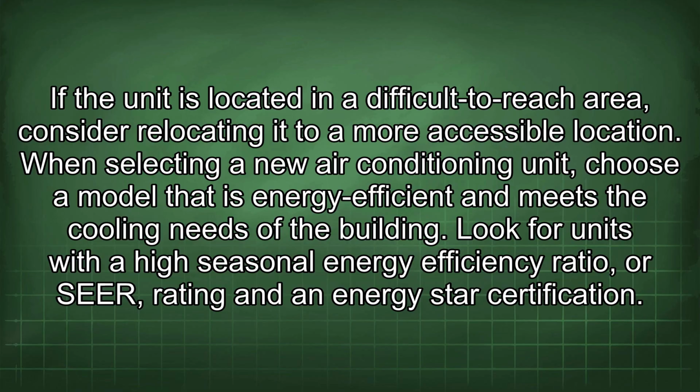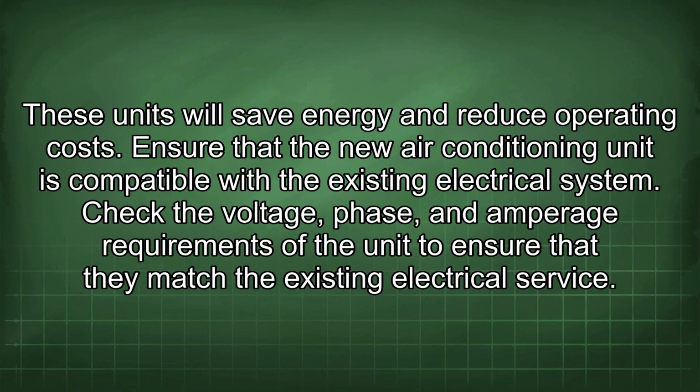When selecting a new air conditioning unit, choose a model that is energy efficient and meets the cooling needs of the building. Look for units with a high seasonal energy efficiency ratio, or SEER, rating and an Energy Star certification. These units will save energy and reduce operating costs.